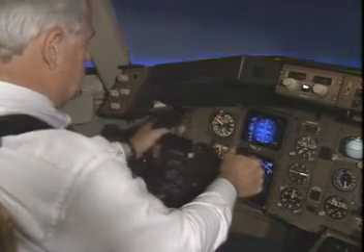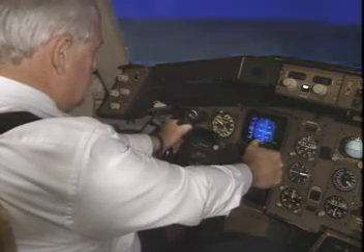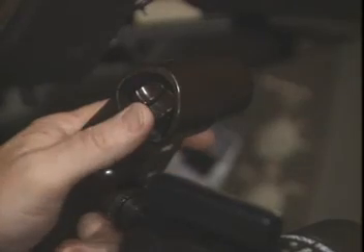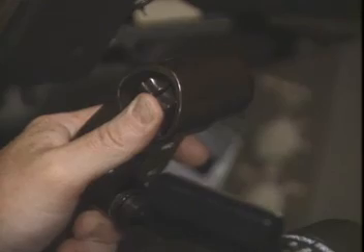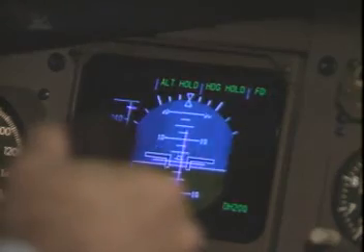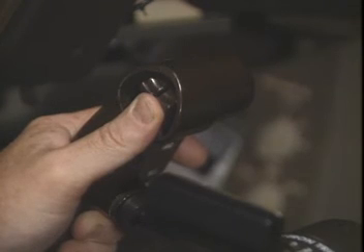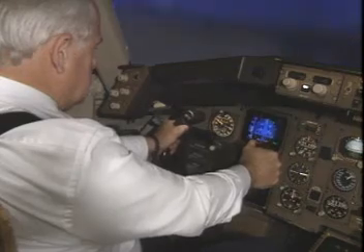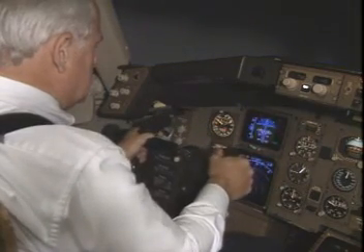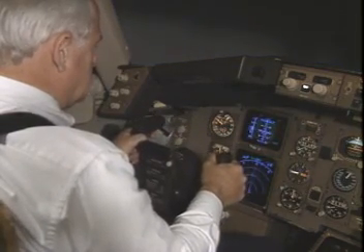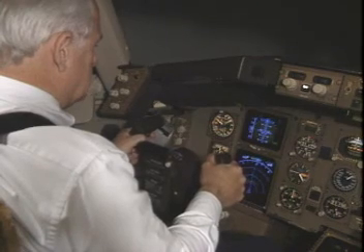If a sustained column force is required to obtain the desired response, you may consider trimming off some of the control force. However, it may be difficult to know how much trim should be used. Therefore, care must be taken to avoid using too much trim. Do not fly the airplane using pitch trim, and stop trimming nose down as the required elevator force lessens.